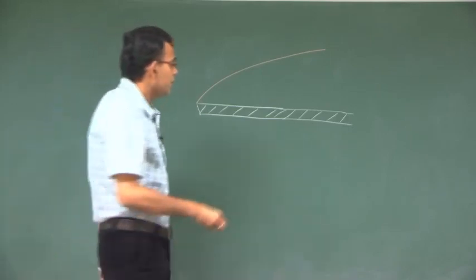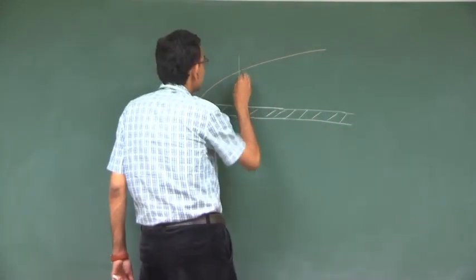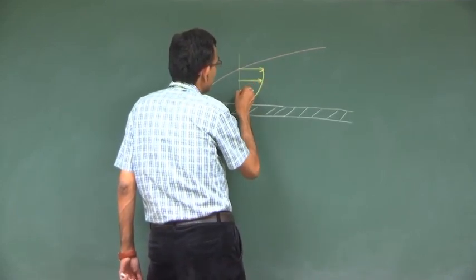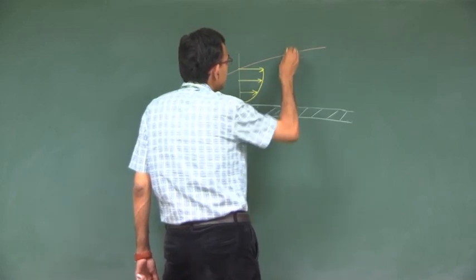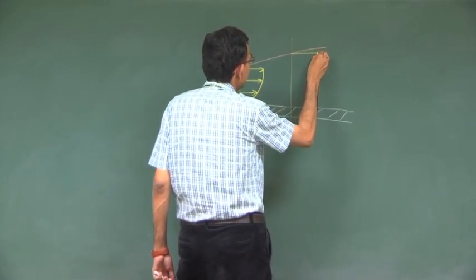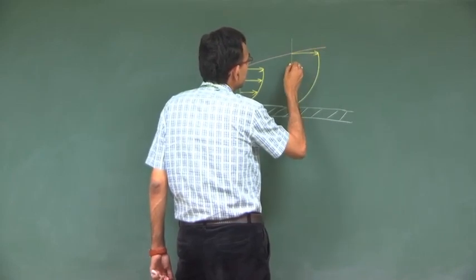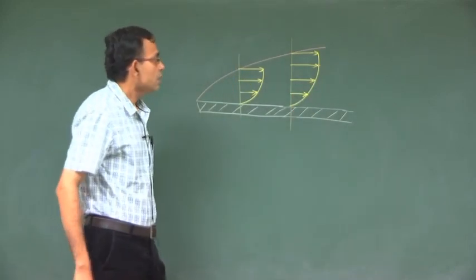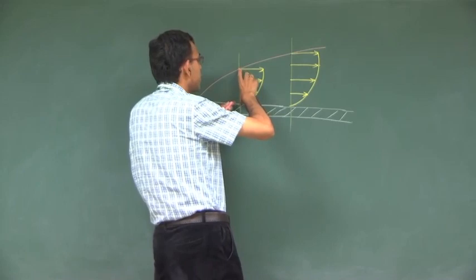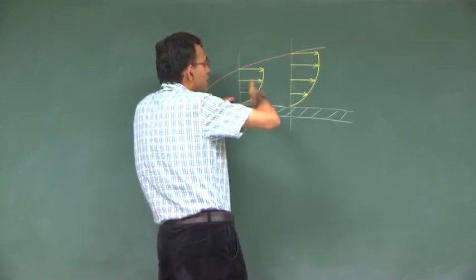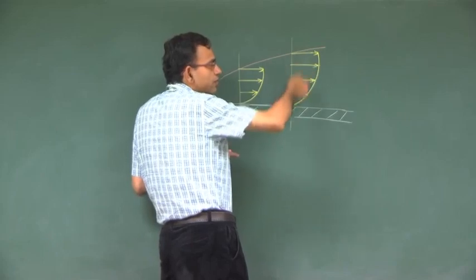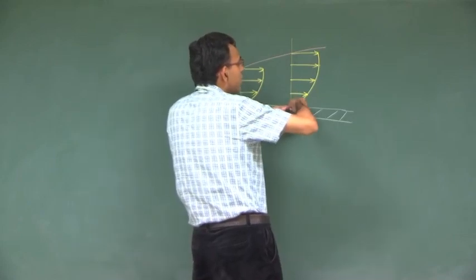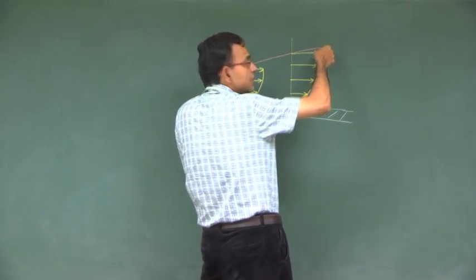Now, if you plot the velocity profiles u versus y, you will see that the velocity profiles are different at different x. The simple reason is that the boundary layer is as if it is getting stretched from this delta to this delta. So, this velocity profile is sort of getting stretched, right. You can imagine that there is a string here, this string when stretched becomes this one.